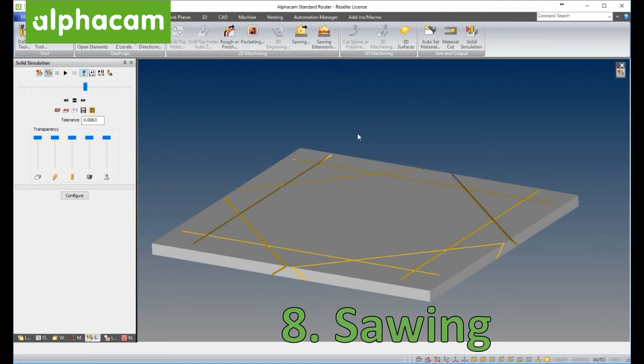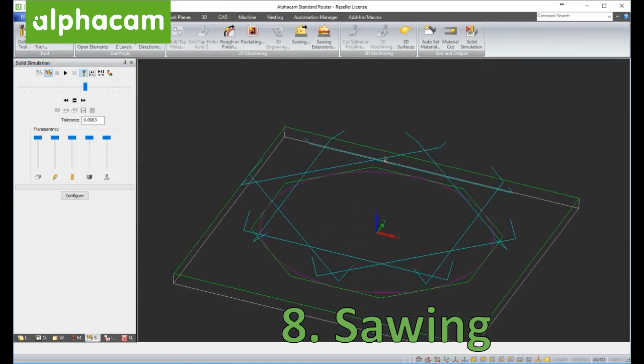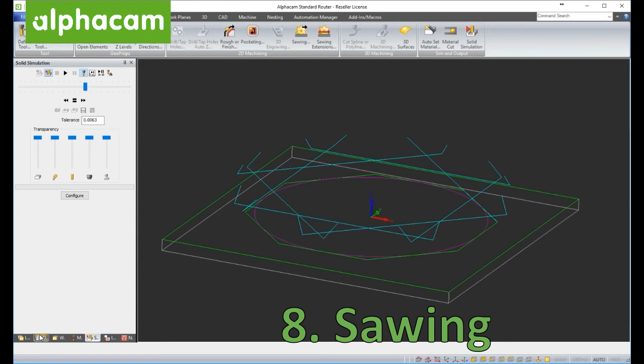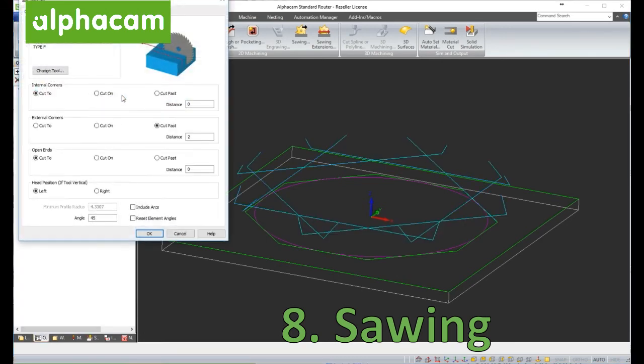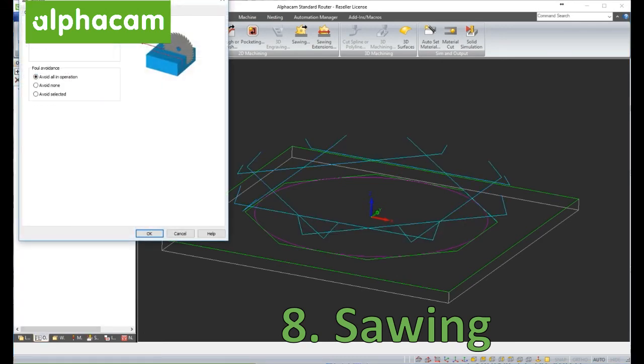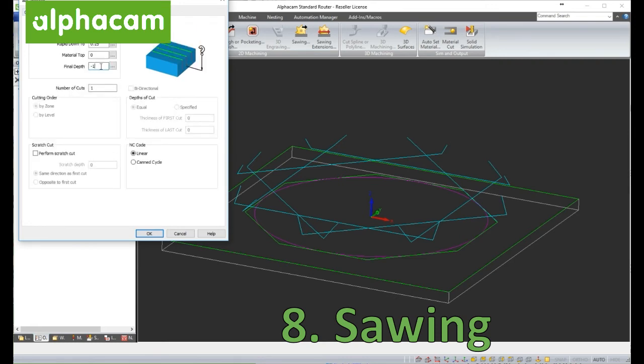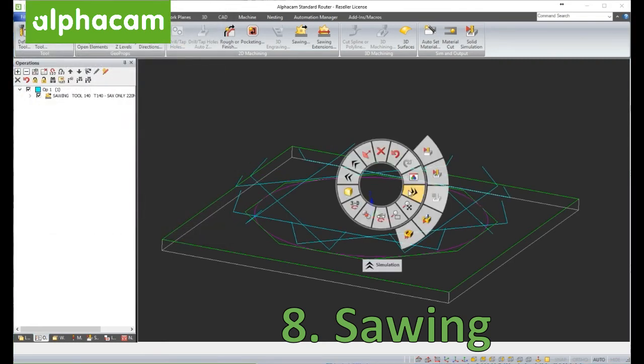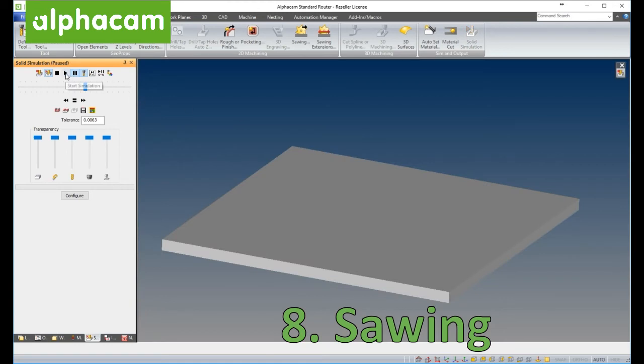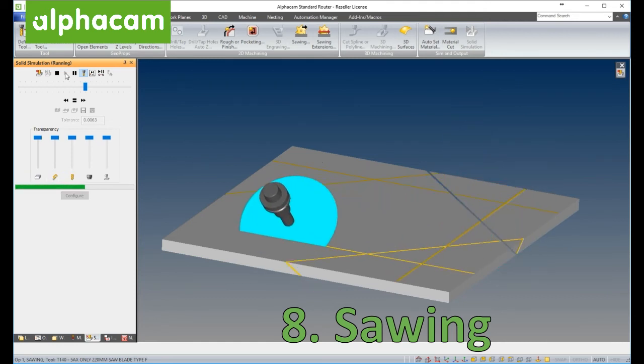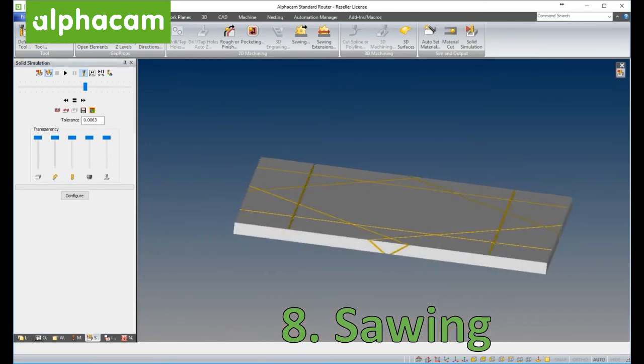Now you can also go ahead and easily extend them, and you can also use the stock to be left to go ahead and make a bigger or smaller feature by simply moving this number. So if I say, hold on, it needs to be an inch smaller and I need to cut a 1/4 inch deeper, you'll notice that now I was able to go ahead and generate essentially a smaller octagon. It's 1 inch smaller than the original green geometry that I drew. But nonetheless, there it is.